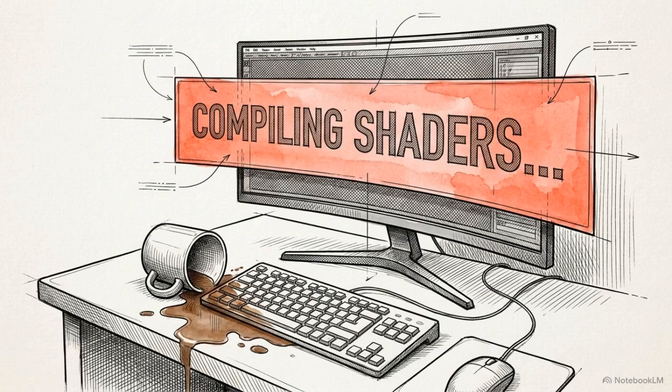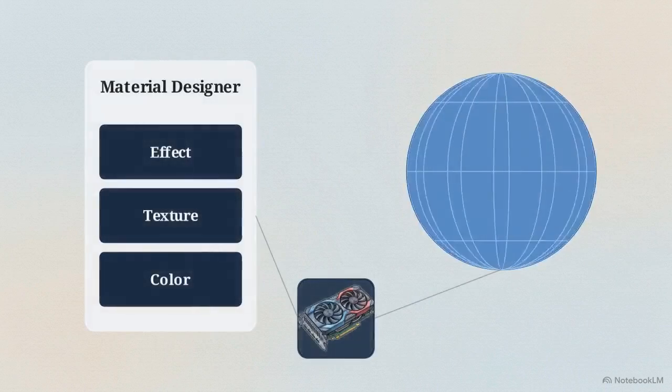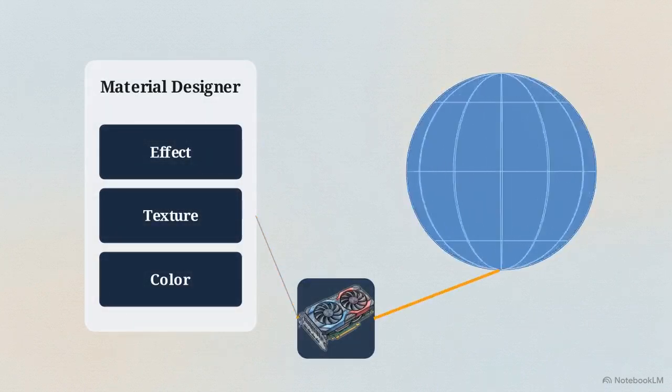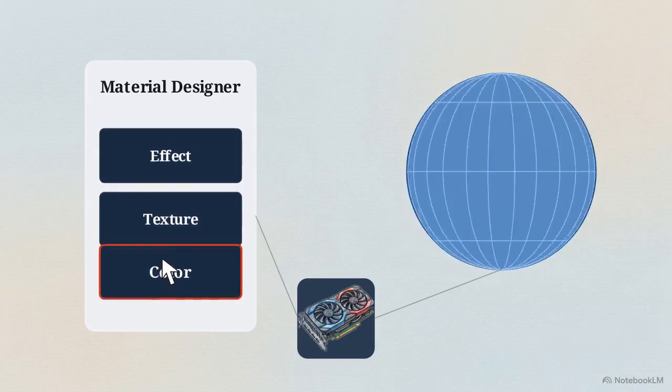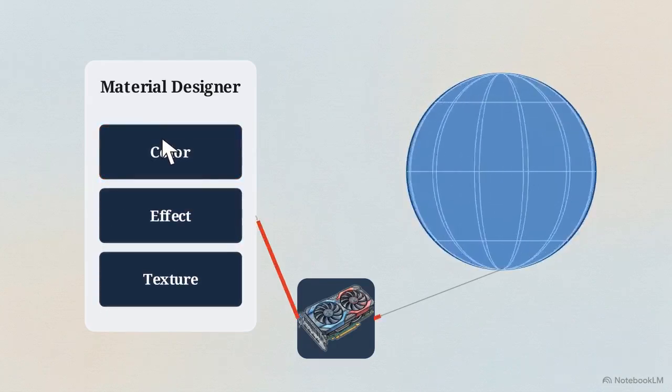Geometric complexity is only useful if the aesthetic can be adjusted quickly. Traditionally, game engine material edits require full shader recompilation, stalling the viewport. This diagram shows the material designer, which uses precompiled parameter networks to bypass those delays. When a designer reorders a layer or changes a blend mode, the system updates parameters in a master material rather than generating new shader combinations.